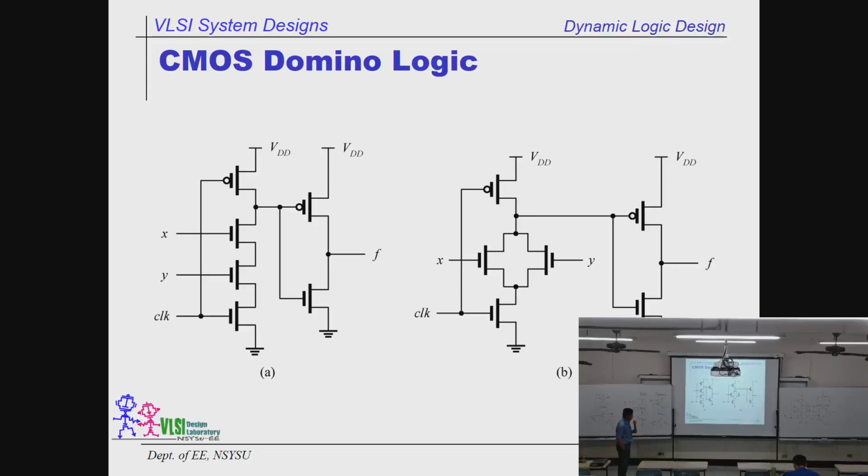That's bad. Anyway, this is the AND gate and OR gate. You realize the domino logic. Look at that. This is an AND followed by an inverter. This is an OR followed by an inverter. These are AND and OR gates in domino logic.